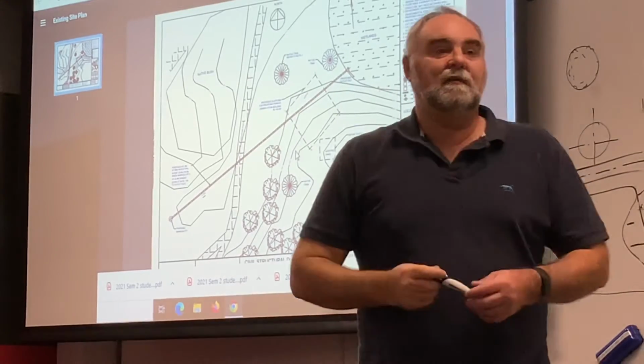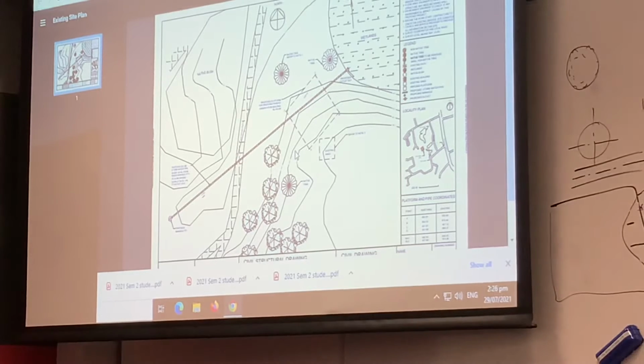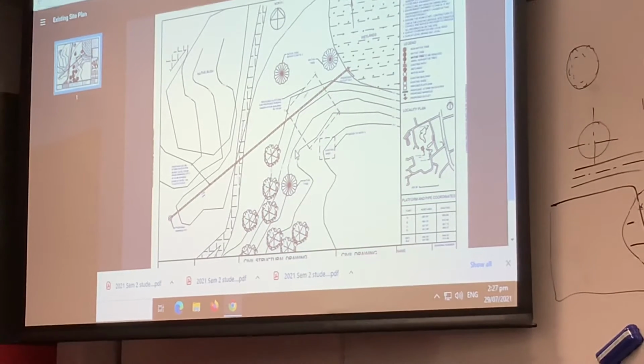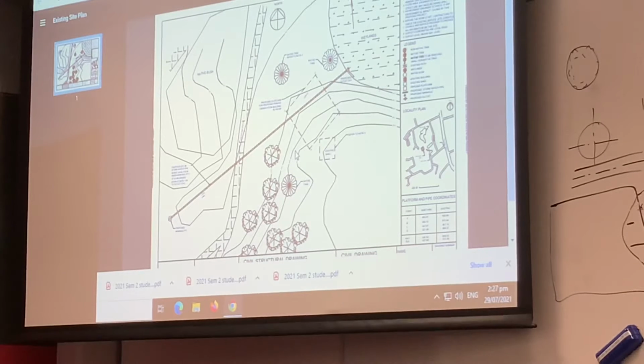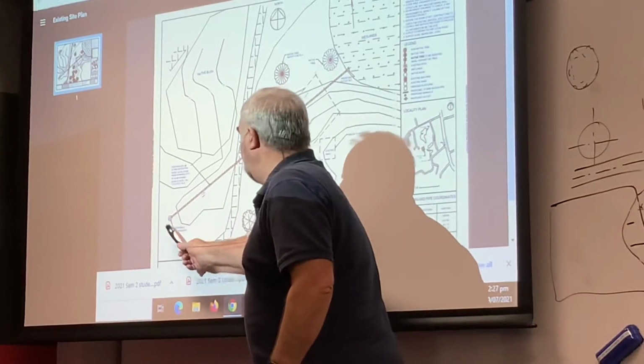Any water, stream, creek, river, wetlands that is draining, and that is a draining wetlands, by the way, you should show a direction of flow arrow, and try and make it a bit different than your normal arrow, like this one here, or this one here.